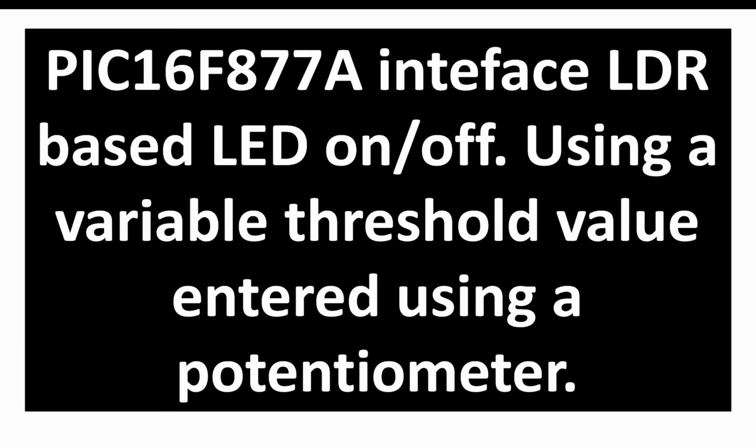In this video, I'm going to show you how you can interface an LDR with a PIC16F877A microcontroller and turn an LED on and off. But in this case, unlike in the previous video, we are going to have a variable threshold value for the LED blinking. Whenever the LDR value is at a certain point, only then the LED will turn on. And we will adjust that value using a potentiometer.